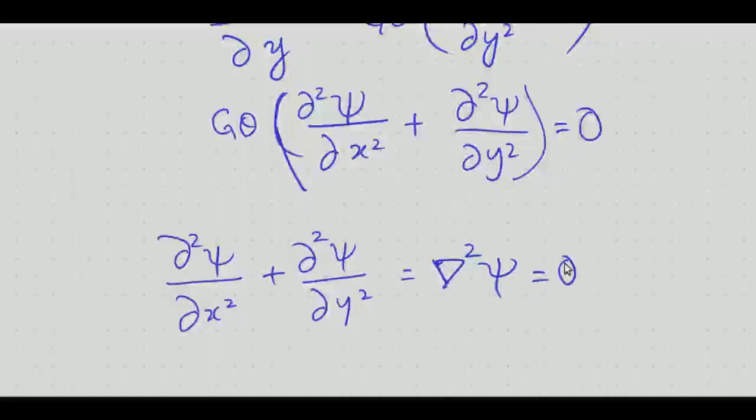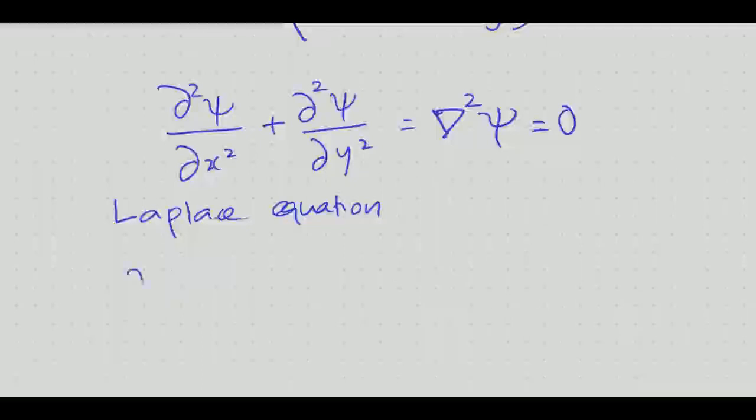So the warping function ψ satisfies the Laplace equation, or we can say that ψ is harmonic over the whole area of the cross section.